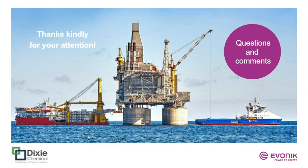But the properties that we're talking about really begin with glass transition temperature, which is the first thing we really need in order to define and understand the behavior of the foam as it is exposed to hotter versions of crude oil and at deeper depths. So it's necessary to understand the heat resistance of these foams, and glass transition is going to give you that